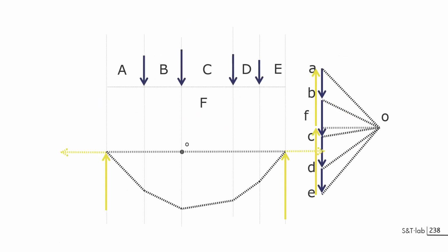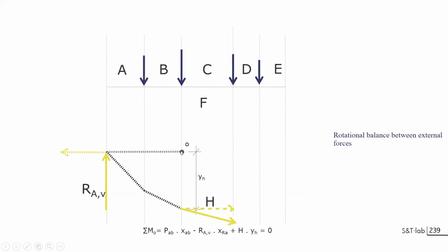So let's move on about the same equilibrium with graphic statics. We have a funicular line here hanging below, let's say, a strut, stabilizing both sides, or just construction line. If you want to make the same equilibrium of this system of force with a pole somewhere, you can cut into the system and make exactly the same equilibrium of forces. So what you have as force will be the force acting here around this point as the reaction force, about this applied force and about the component that could be a part of the bending force applied to this line. For this, you have to take the horizontal component and the lever arm that will be perpendicular. In this case, it will be vertical.